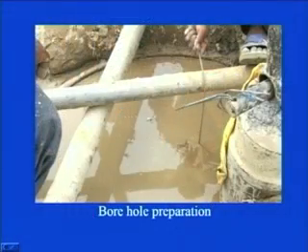This bentonite slurry gets in contact with the wall of the borehole, and for the time being it strengthens the wall of the borehole. So, you can see here that it is filled with this bentonite slurry. You can see this is the circumference of that borehole, this much part is being seen here in this particular figure.